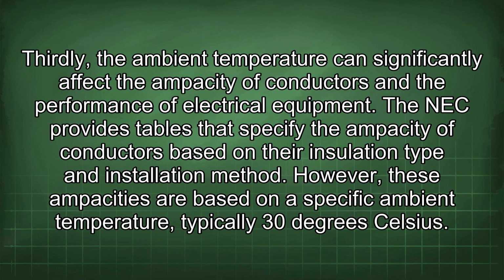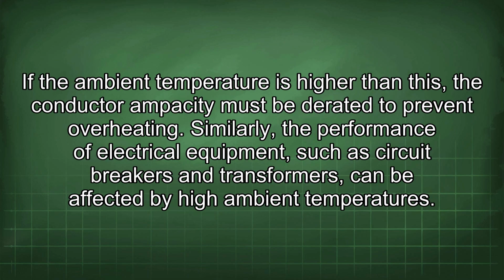Thirdly, the ambient temperature can significantly affect the ampacity of conductors and the performance of electrical equipment. The NEC provides tables that specify the ampacity of conductors based on their insulation type and installation method. However, these ampacities are based on a specific ambient temperature, typically 30 degrees Celsius. If the ambient temperature is higher than this, the conductor ampacity must be derated to prevent overheating.